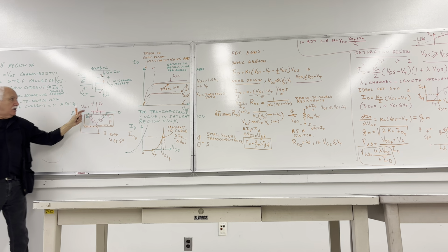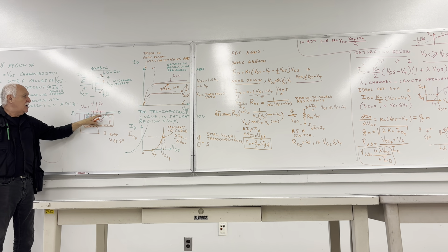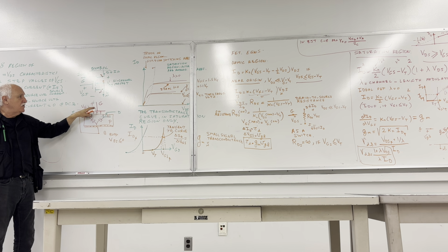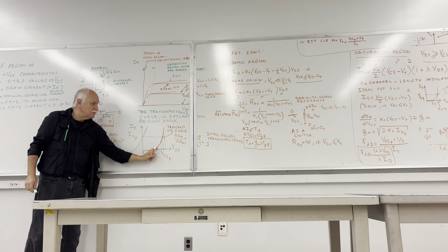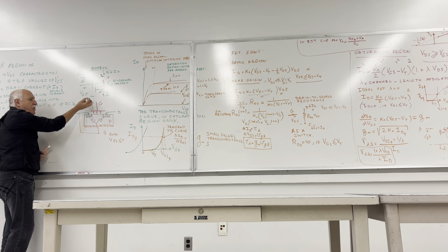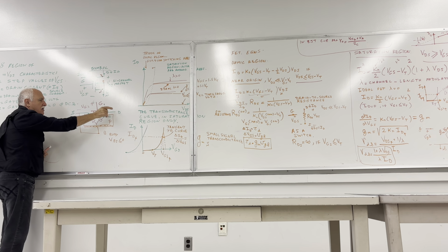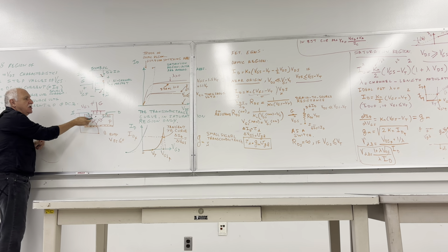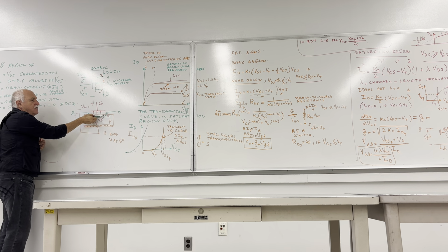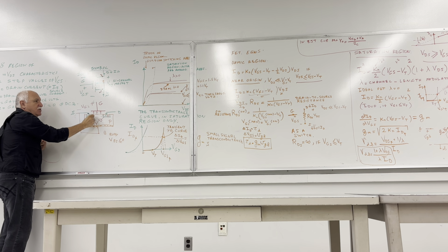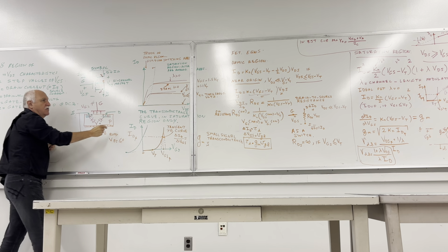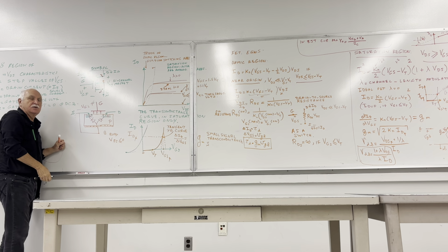So this is the structure, and I talked about the buildup of electrons underneath the layer from the p-type by influence of electric field coming from the gate, which is due to the gate to source voltage. So once the field exceeds, it will attract electrons from the bulk, lay them underneath. Electrons can conduct then. Initially, that layer gets thicker and thicker for small drain to source voltage. So layer gets thicker, it means resistance will be proportional to the VGS. That will be the linear region, just like an ohmic region.